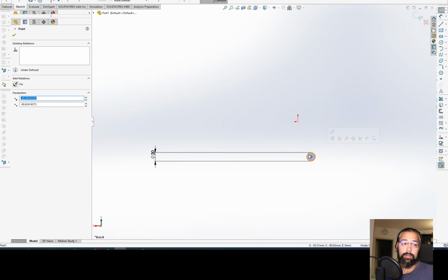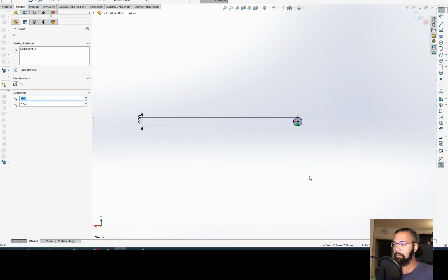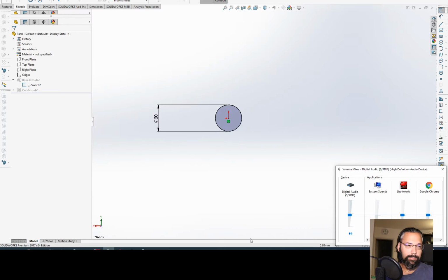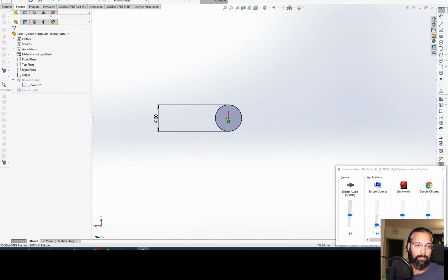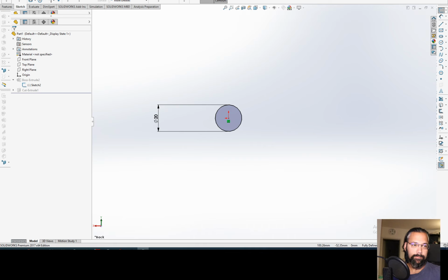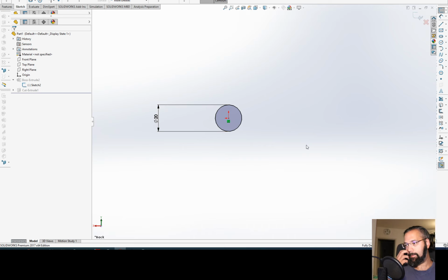And then you can do a few things. Usually if it's the first sketch, you drop it onto the origin and everything becomes black. You're happy. Here at the bottom you can see, you can see here, this says fully defined. And fully defined is the criteria under which you are allowed to close a sketch.